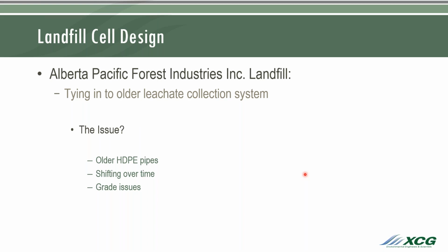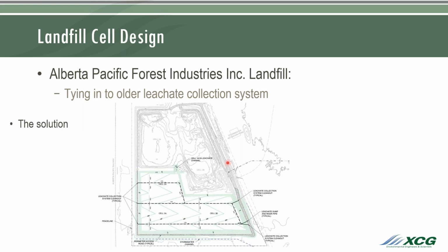They'll lose their structural rigidity, so your HDPE pipes will oval on you. They'll shift. The landfill's constantly moving, and the grades are constantly moving. As you pile waste high up, it exerts a force down, and you'll actually get a little shift in your landfill grades. So it can often be difficult to find the tie-in points between your new and your existing landfill leachate collection infrastructure. So the solution that we went to was to break the landfill into a couple of different